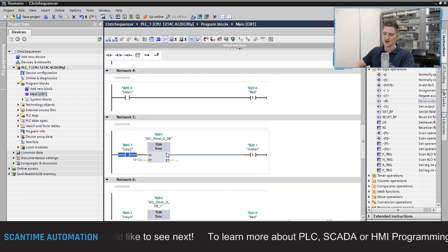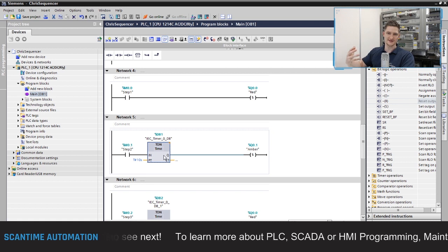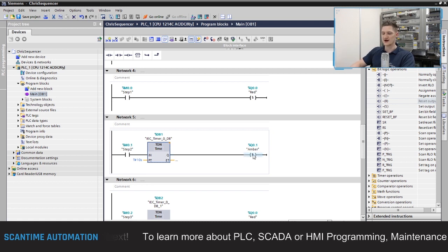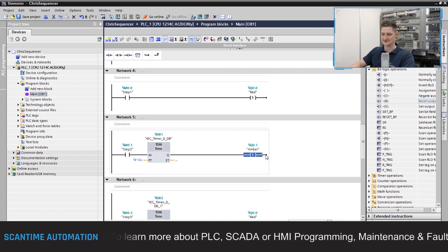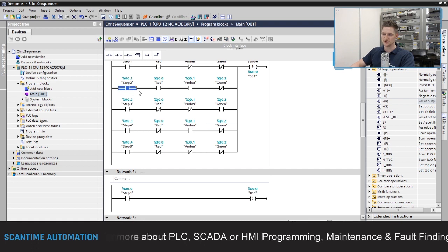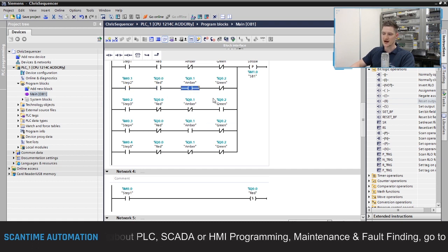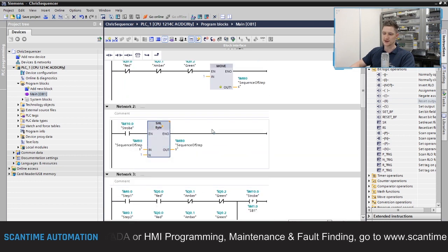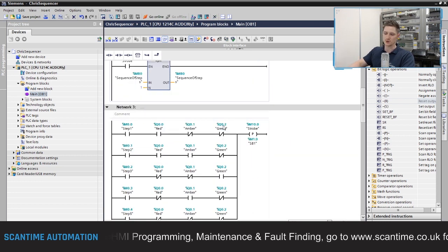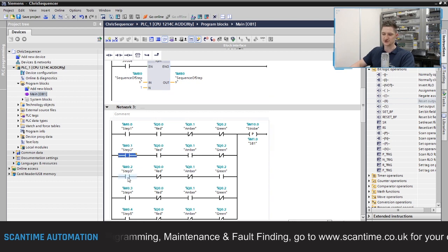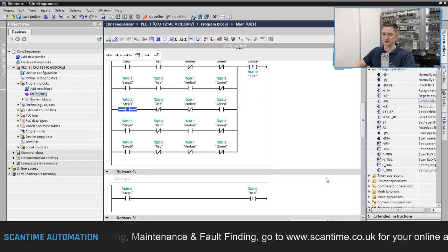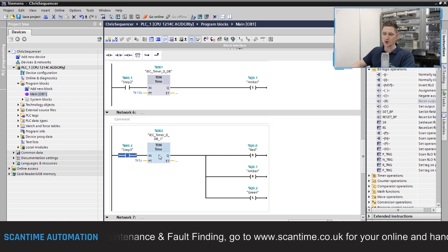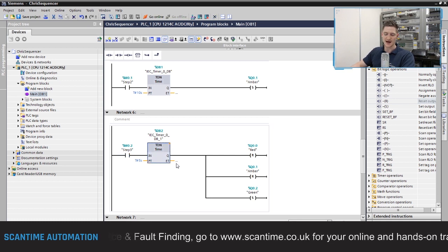Our step 2 then waits 10 seconds, allowing the red to be on for 10 seconds, and then after that 10-second period, it then sets the amber. Step 2 is now true, red is now on, amber is now on, and green is now off, triggering the strobe signal, triggering our shift register, moving the bits one place to the left, turning off step 2, turning on step 3.